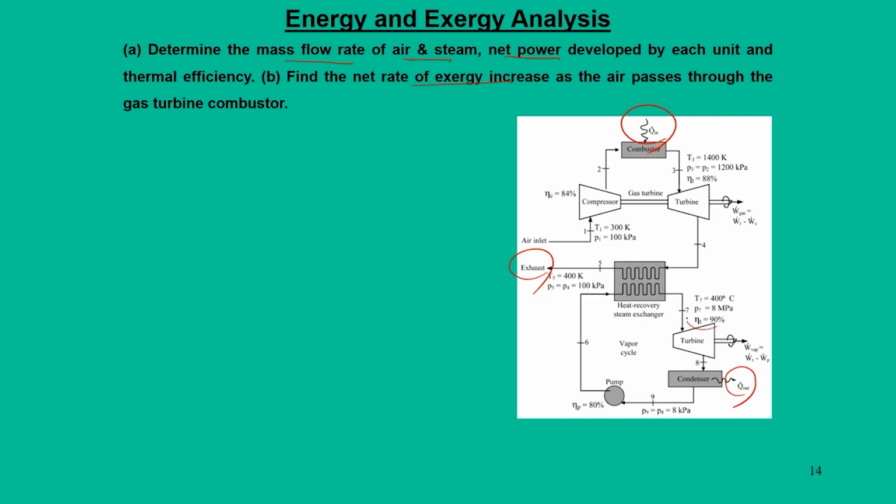Since these components operate at different conditions, the exergy lost in the steam turbine, the exergy lost in the gas turbine, and the exergy lost in the heat recovery unit all have to be calculated. Then we need to perform the exergy balance, or account for the exergy which is lost, and with these numbers we can predict whether the justification of the steam and gas turbine unit is verified or not.